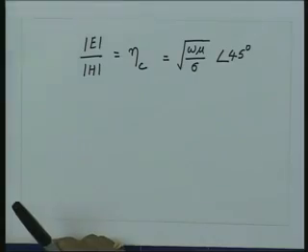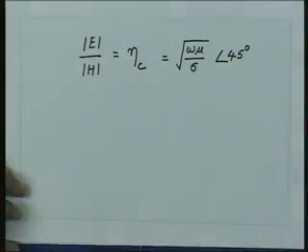So, when we talk about a good conducting medium, important things happen. When the wave tries to penetrate the conducting medium, it penetrates over a very short distance, what is called the skin depth, and also the electric and magnetic fields are not in time phase anymore, but there is a phase difference in time between them, which for a good conductor is approximately 45 degrees. So what we find from this discussion is that wave propagation in a dielectric medium and in a conducting medium are completely different.